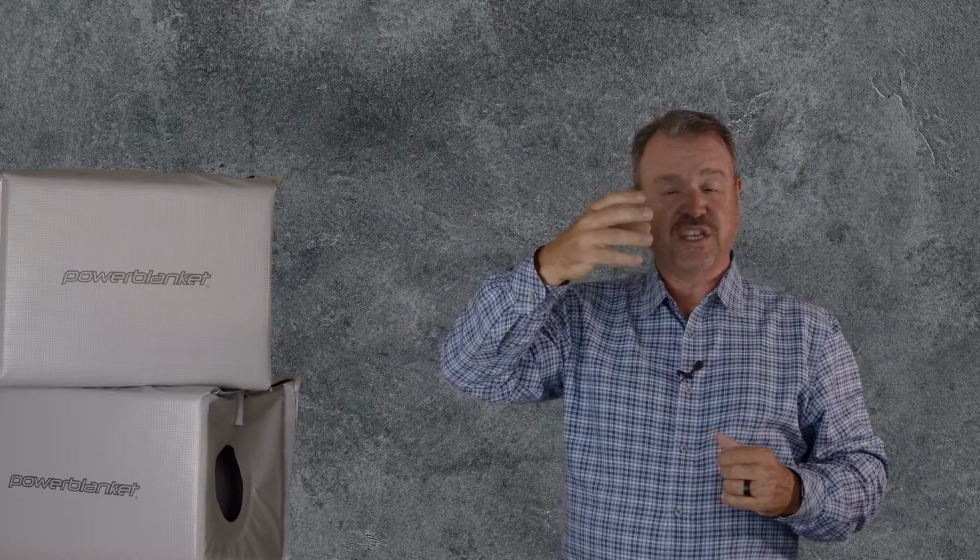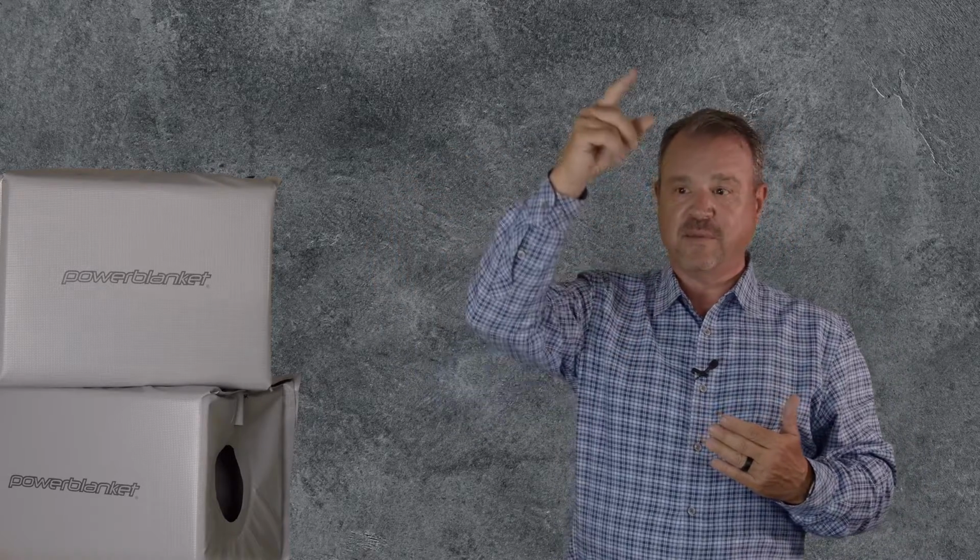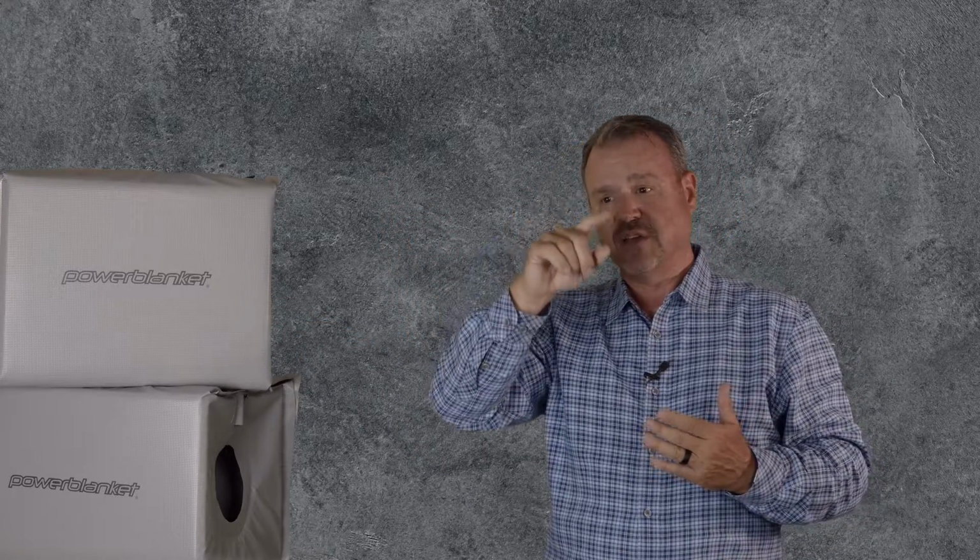Circulation heaters are probably the most sophisticated type of electric process heater out there. They really are a heat exchanger. An electric heater is placed into a vessel or a chamber, and the elements hang out into the chamber. The vessel has an inlet and an outlet that are flanged connections normally to a process, and product flows through that heater out into a process. So heat is exchanged from the electric heater to the product flowing through it.